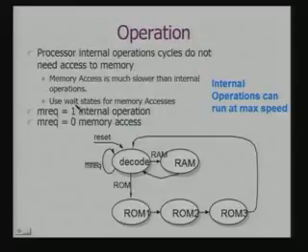Wait states will get inserted only when the processor explicitly requests a memory access. That is the basic significance of this MREQ signal which is coming out of the processor. MREQ 0 clearly indicates a memory access, and MREQ 1 is an internal operation. So when it is MREQ 0, I go to the RAM decode, go to the RAM and come back, and when I am doing the access here, it is a ROM access, and corresponding to that the wait state would be generated. So this MREQ signal indicates at what point the wait should really be made active when we are doing a ROM access.